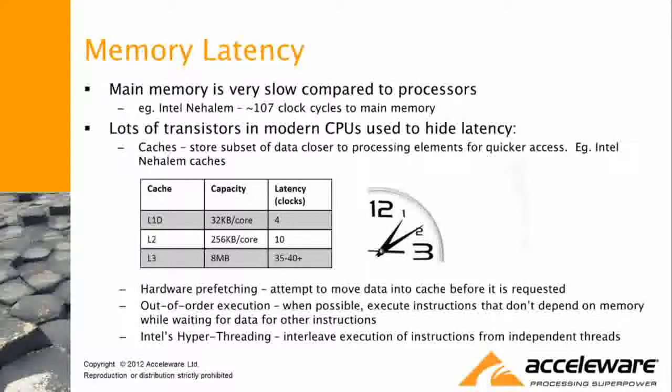Main memory, regardless of whether you're on the GPU or CPU, is relatively slow. And what Intel does is they've done a really good job of trying to, as programmers, mask what's actually happening. So they build all these layers of cache that are trying to store values on chip so that the latency between when you issue a memory request to when it actually appears in the register is low.